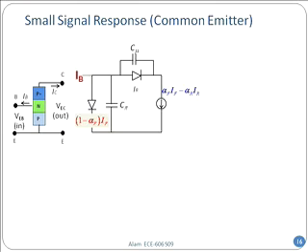Then you should have this particular circuit where you had 2 diodes, one going from the base to the collector on the other side, and the C pi and C mu are essentially the various junction capacitances. So this is something you should have had. If you don't know how to do this, perhaps you will go back and look at that one more time. But for the time being, assume that this is what it is. Let's proceed with this one.